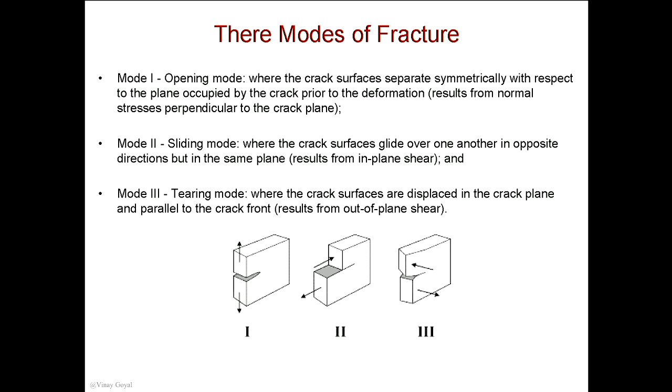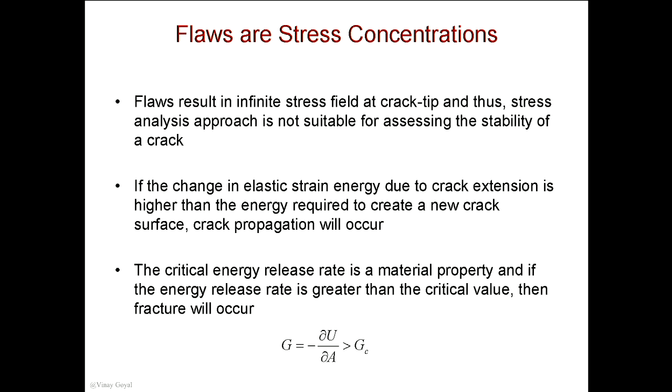So for example, if I have a crack tip that's slanted, what I could do is maybe look at the max principal stress or the stress that will open that crack and perhaps follow that instead. But that is a much more complex subject. So for now, we're going to focus on mode 1 crack propagation, okay, for the time being.